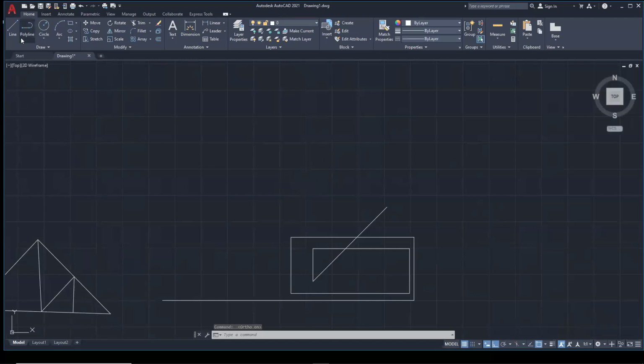I'm gonna just use the line tool here, and I'm gonna left click. And now, no matter where I move my cursor, that line is horizontal. I'm moving my cursor all over the place, and AutoCAD isn't cooperating with me. It is only going to draw that line horizontally, and again, horizontally or vertically.